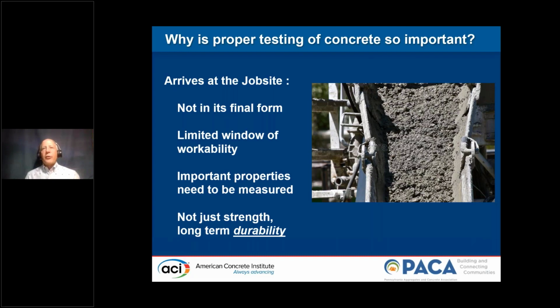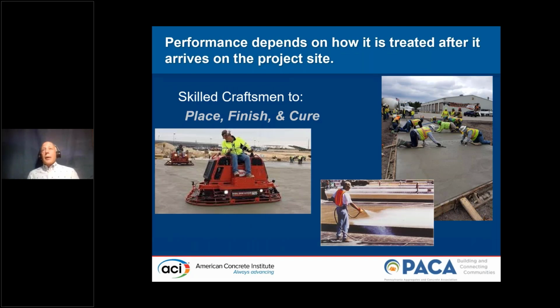One of the most important reasons that we need to test concrete properly is because it is the only major building material that comes to the job site not in its final form, and it's a perishable product. But it also has some very important properties that we need to measure. And we're not just talking about strength. We have high expectations of our concrete, and that means we want it to be durable. Its performance is also dependent upon what happens to it after it gets on the job. We rely on these folks to place, finish, and hopefully cure concrete properly and professionally.